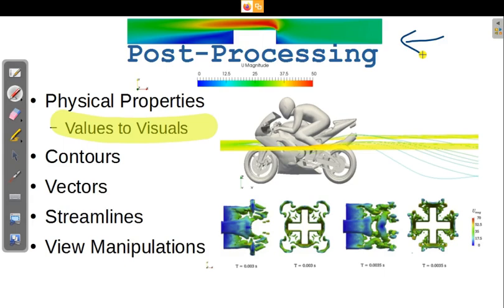You have a flow which is moving above that particular box, shown in red color, which means acceleration of fluid. So this color says that it is of higher velocity. You see that legend shown below this post-processing. This is the U magnitude. Red color stands for 50 meter per second, which means this has an acceleration process there.